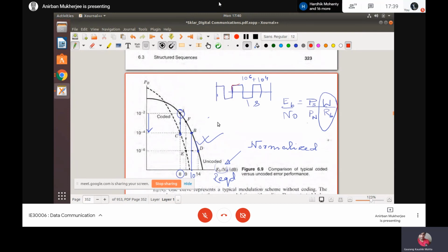Now, what you have to do? You have to reduce it. Then if you reduce this, if you take the Fourier series and all these things, you cannot transmit like this, you have to transmit maybe the fundamental, first harmonic, third harmonic, say seventh harmonic. That means you are sending F0, 3F0, 5F0 and 7F0. Because after that all the amplitudes will be very small.